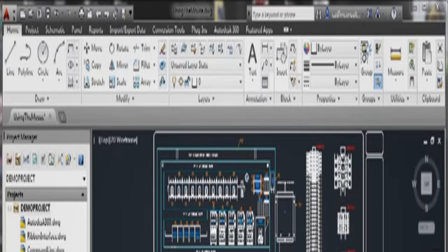Also as well, your left-hand mouse button tends to be your select tool. So if I hover over, let's say, that line there, you can see it highlight. AutoCAD has a default highlight setting, so if I click now using the left-hand mouse button, you'll see it actually selects that line that forms part of that panel layout. If I hold down the Shift key on the keyboard and then left click again on that line, it deselects it. Just a click on an object will select it, holding down Shift and a left-hand click will deselect it.